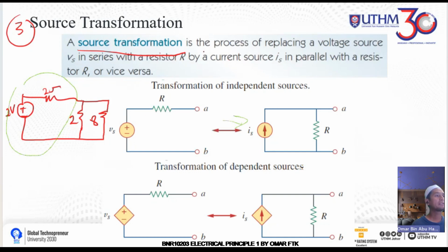So source transformation is the process of replacing a voltage source in series with a resistor by a current source in parallel with a resistor, and vice versa. It's like a tool to help you do the analysis.